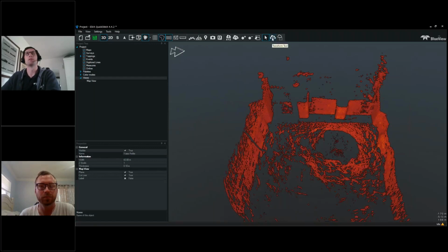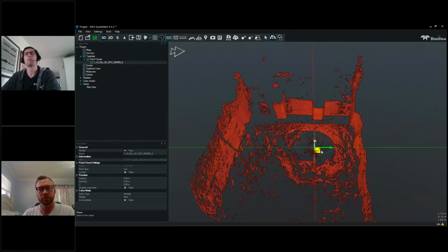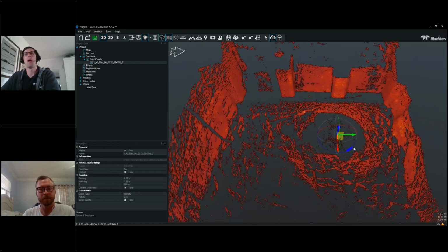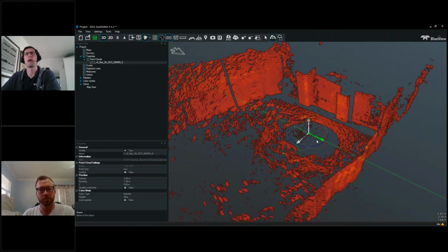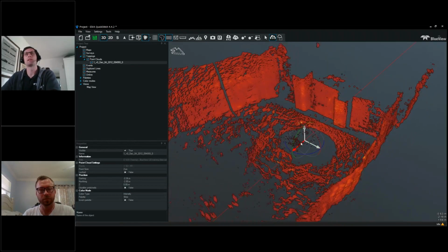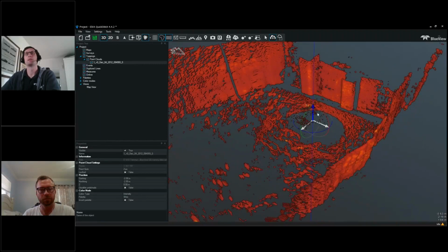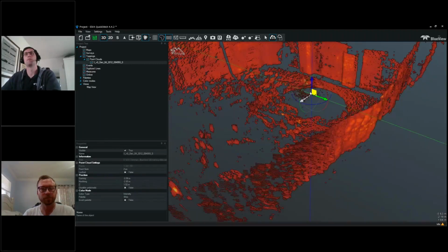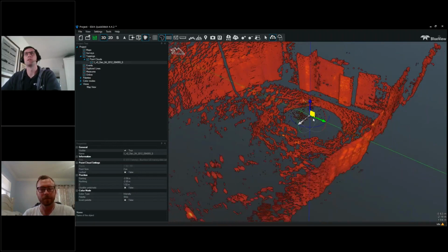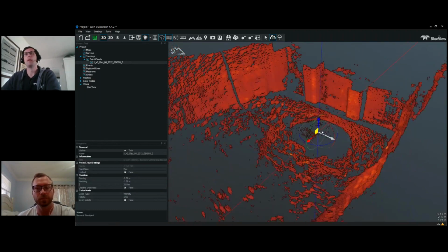The transform tool is actually a movement tool. I get these controls that pop up. Let me zoom in a bit. We have a number of controls here, controls for each axis. If I click, say, the green arrow, it's going to move just along the y-axis. If I click the red arrow, x-axis, and the blue arrow, it's going to move just along that single axis. So single axis movements are these arrows. And then if I click these yellow handles, that's going to be double axis movement, or movement along a plane. So here's along the YZ plane, the XZ plane, and then the XY plane.